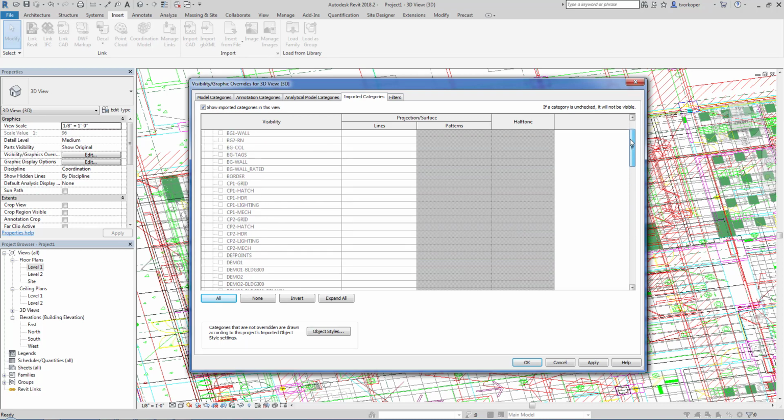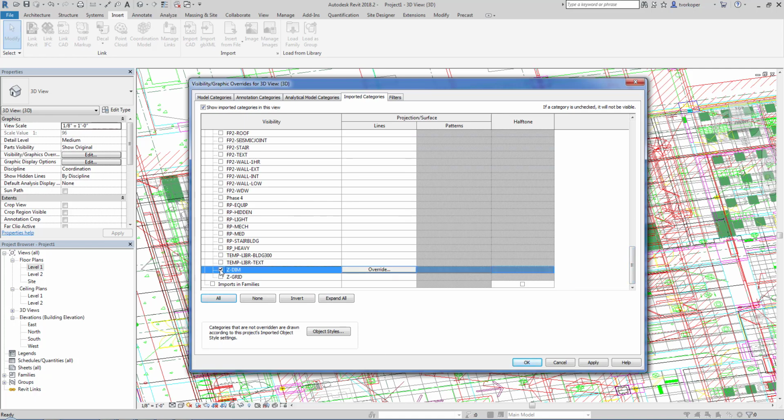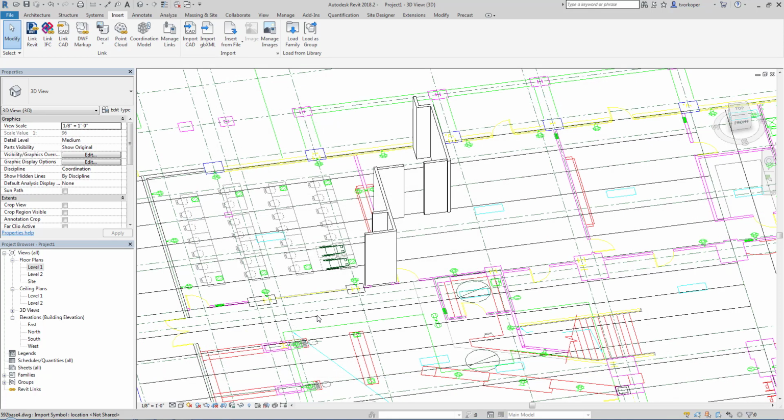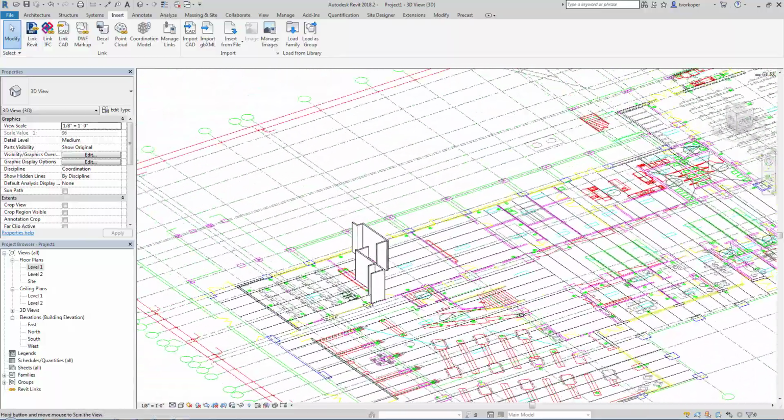When we turn them all off, we need to make sure that we go back and turn the main one, the root or the parent, back on. So now we can select these. And we'll turn on layer 0, and we will turn on a couple of the background layers. And then we'll come down to floor plan 1 and turn on all the floor plan 1 layers. And lastly, we'll scroll down and turn on the dimensions and the grids. And now you can see floor plan or level 1 that we've been modeling on.